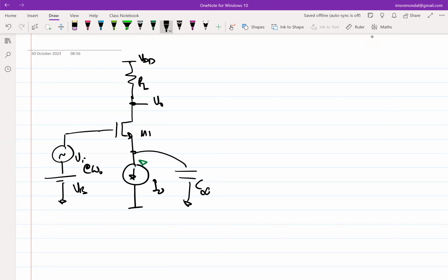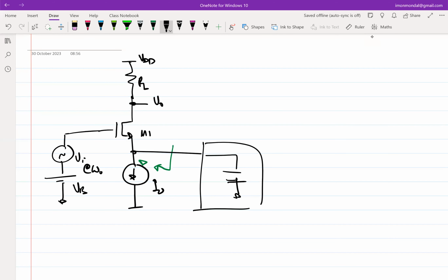Yes. So what will be that equivalent R? What we are seeing at the moment. Right. So I have to Thevenize the circuit. Whatever the capacitor is seeing, I have to find out the Thevenin equivalent resistance looking this side. So you can assume that you have a box. Inside the box, you have a capacitor. But I'm trying to figure out what is the Thevenin equivalent resistance looking here, right? What is the RTH? If I know this RTH, then I know what is the value of this capacitor that is required. So what is the RTH?